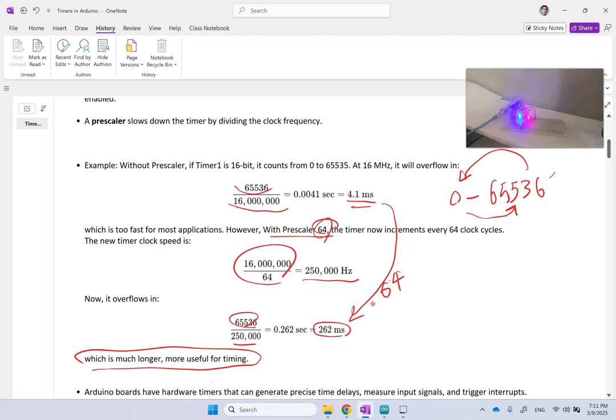because 4 milliseconds is super fast. Before you know it, it's over. If you want to do any mechatronics task with it, 4 milliseconds is very fast. Most of your physical systems are not that fast, so you need to slow down, as I said.